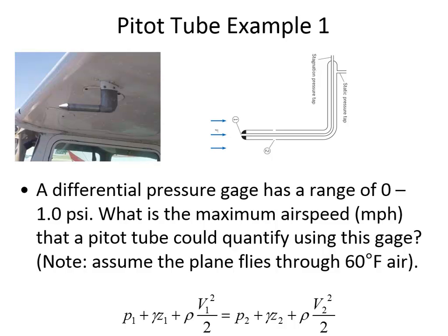These feet go up in the numerator, so it's feet to the 4th divided by feet squared. That leaves us with feet squared in the numerator. These slugs cancel out and the seconds are in the denominator, so it is foot squared divided by second squared, to the 1/2 power, and that's how we end up with the foot per second.